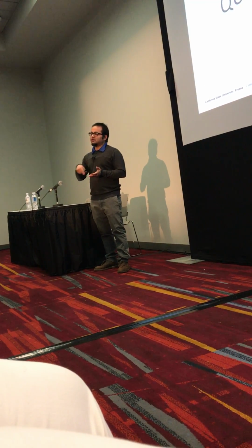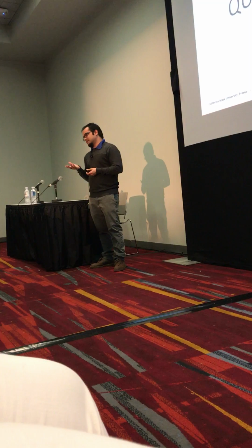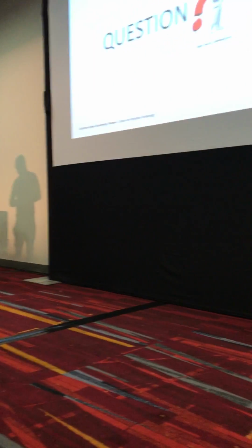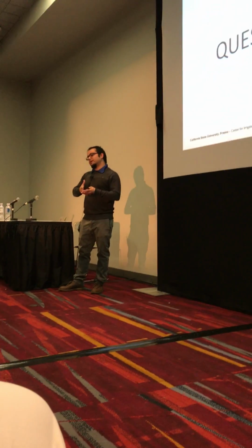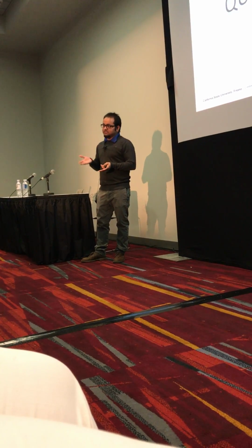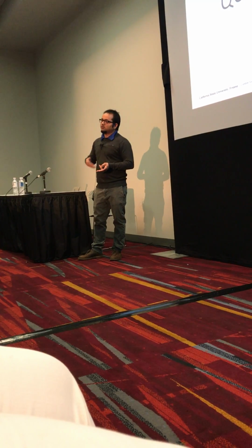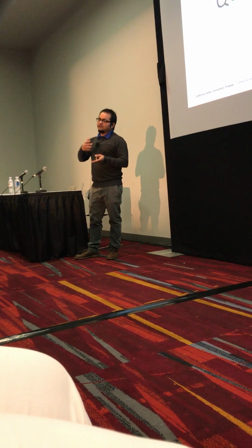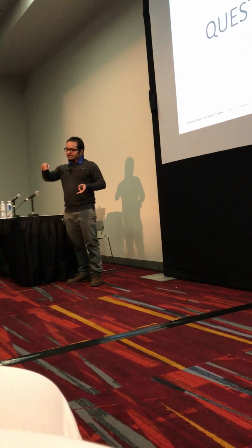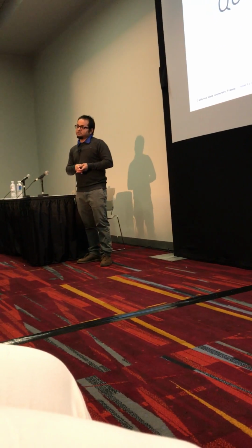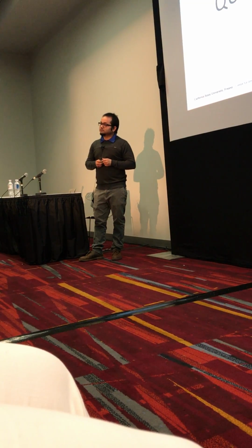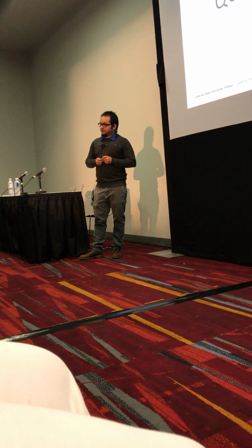They have something called a sphere of influence, because they're electrical sensors, so they emit electrical pulses. If we have a longer sensor, let's say a 6-inch sensor, we have to decide what kind of container to use so that we can pack it well enough that the sphere of influence doesn't get affected by the metallic cylinder from the surrounding areas. So the sphere of influence in each container was appropriate to the individual sensor?